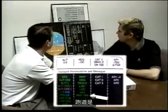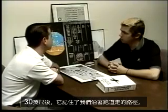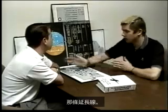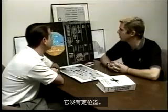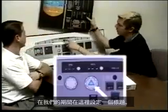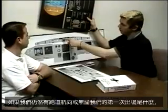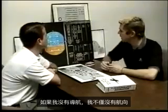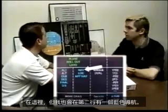Runway track? Runway track is, after 30 feet, it memorizes the path that we took along the runway, and then it presents us with a flight director display to maintain that extended line. Runway track's available on all runways, regardless of whether or not it has a localizer. The only time we won't see runway track is if we forget to, or intentionally don't, set a heading in here during our pre-flight. If we select runway heading or whatever our first turnout's going to be, we're basically de-arming nav. If I didn't de-arm nav, not only would I not have a heading in here, but I'd also have a blue nav on the second line.